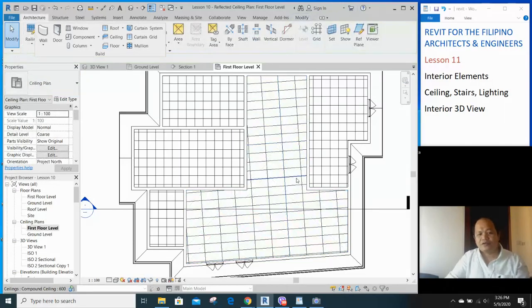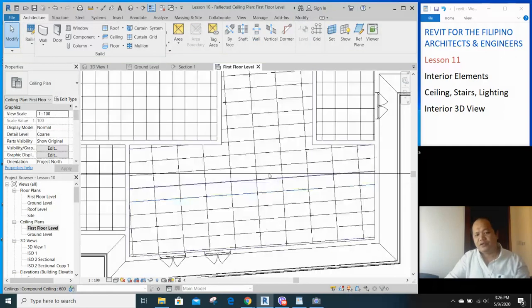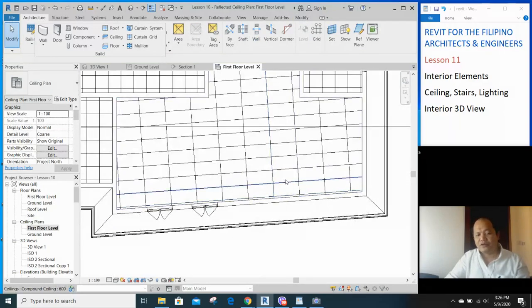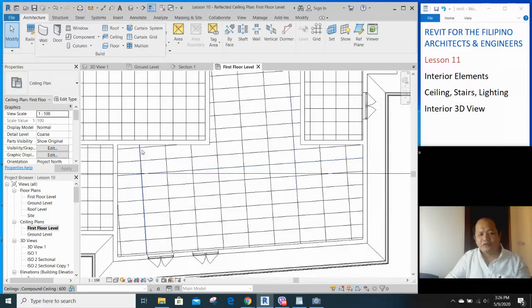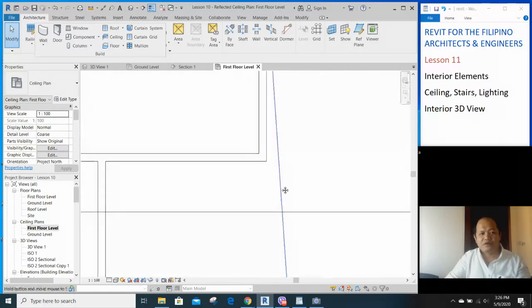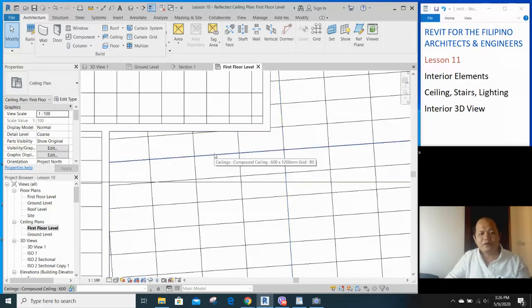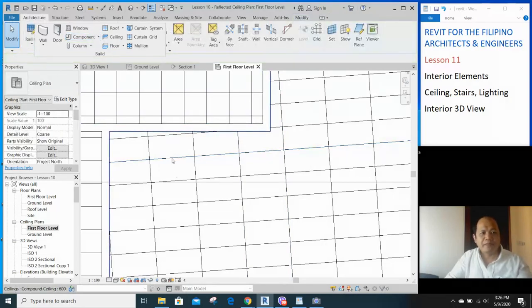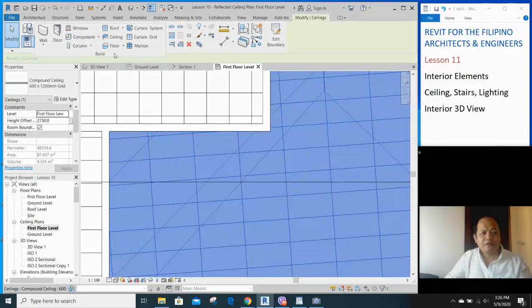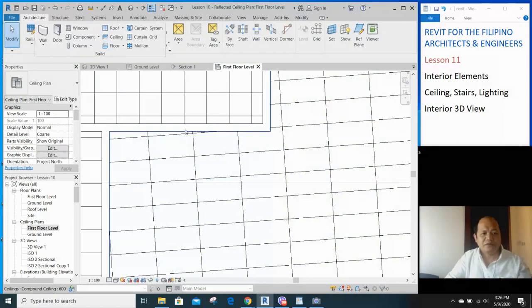And you'll be asking, can we change the line or the orientation of the ceiling? Yes, of course. If you want to align it with this wall, what you simply do is click your ceiling and click on align. Where's align? Click escape. Select the ceiling, then where is our align? Modify tool. No, sorry.